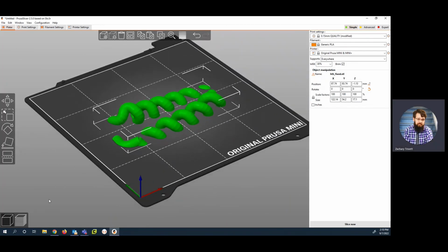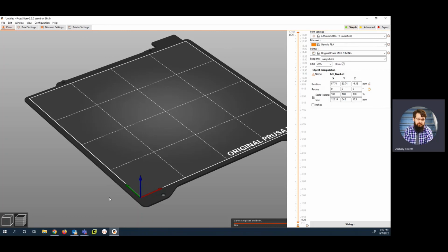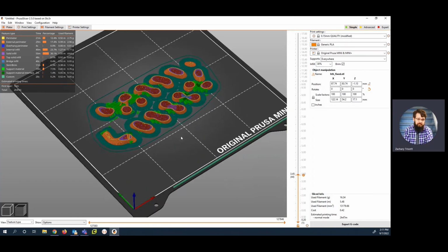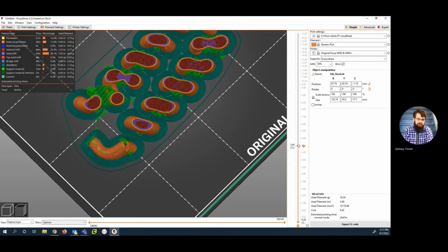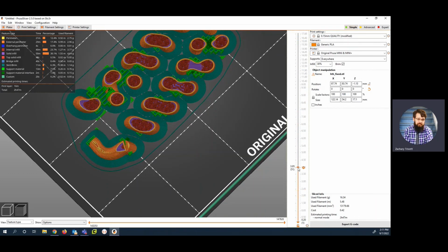Now, before you slice it, you can go here to the bottom left and go to a preview. What that's going to do is kind of slice it beforehand and show you what it's going to look like. On the right, you will see that this is going to be printed in about 176 layers. I can go through all of these layers and see this is where the infill comes into play. I can see that it's infilling with this particular design. So it's not a completely solid material, and I can go through here and analyze what's happening.